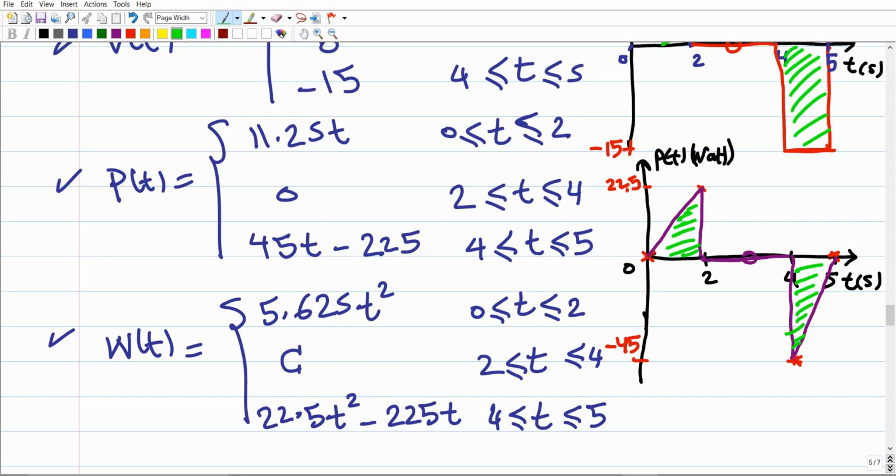So to be more accurate, to describe this figure we say that within the time period between 0 and 2, the inductor delivers electric power, and within the time period between 2 and 4, there is no electric power through the inductor. But beyond this, between 4 and 5, this inductor takes power, or dissipates, uses or consumes power, kind of.